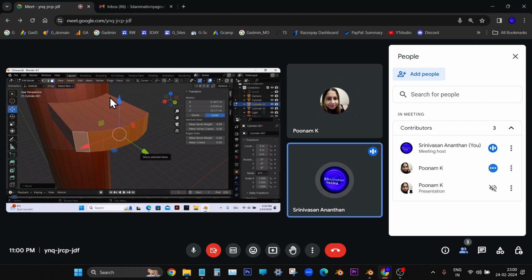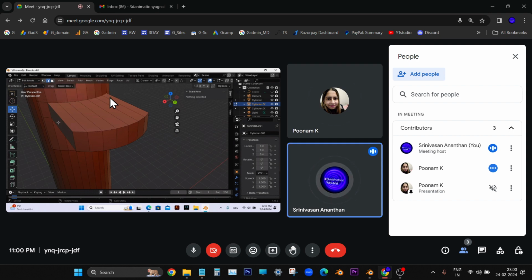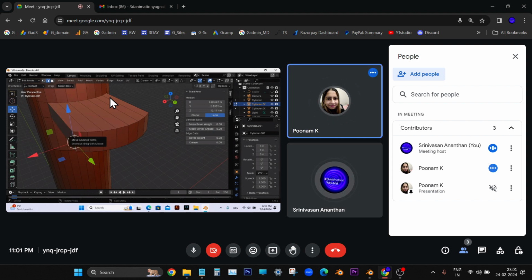Enough. So we'll have a provision for making a hole for that one. Right. Now Alt A, go to edge mode. Edge mode, yeah, middle one, and select the left side edge on the recently duplicated vertical edge. Yeah, same on the right side, shift select on the right side.